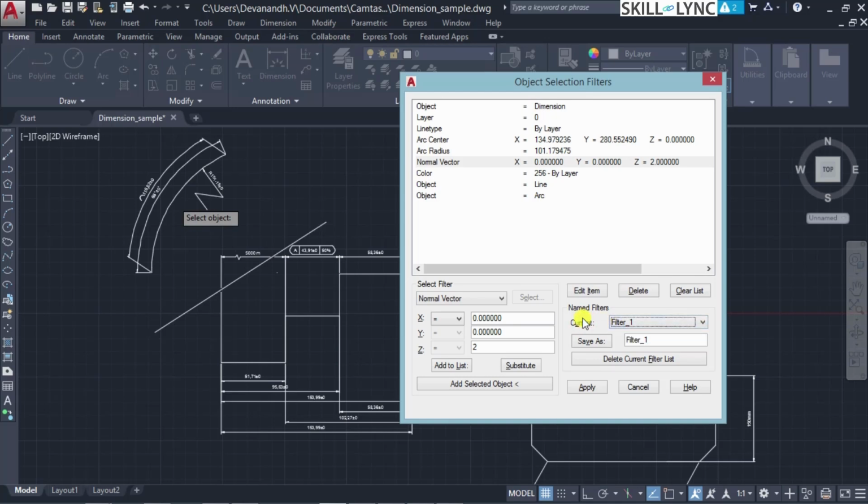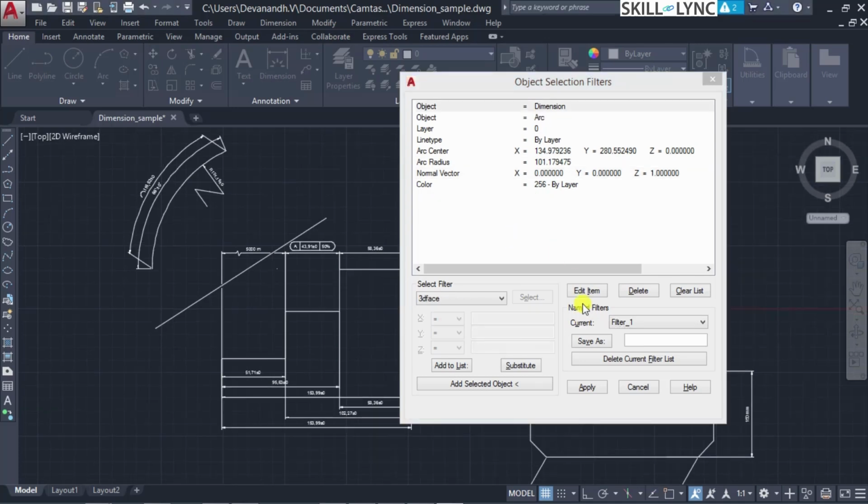This will be very useful if you create certain named filters that you can apply across each and every drawing you have. That is, you can create filters based on dimensions, or colors, or text properties, so that you can categorize them. Categorizing them will be helpful for the layer-based separations that we look at subsequently. So this is how we have created this filter layer.